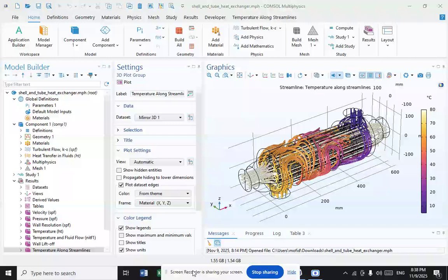Plate heat exchangers also differ in the types of plates that are used and in the configurations of those plates. Some plates may be stamped with chevron, dimpled, or other patterns, whereas others may have machined fins and/or grooves. When compared to shell and tube exchangers, the stacked plate arrangement typically has lower volume and cost. Another difference between the two is that plate exchangers typically serve low to medium pressure fluids, compared to medium and high pressures of shell and tube.